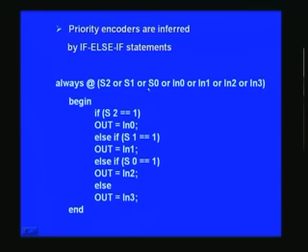So the next thing we are going to see is once again already covered. It is a priority encoder as such, and this is the always block which brings out the priority encoder. First, this is given the topmost priority. For example, there are 3 inputs, you can regard it as a single 3-bit input, or as 3 different inputs. S stands for the select. So we have 3 selects here, and we have 4 inputs once again. It's also a mux basically, and you need to get either in 0 or in 1 and so on, depending upon S2, S1 or S0 in this fashion.